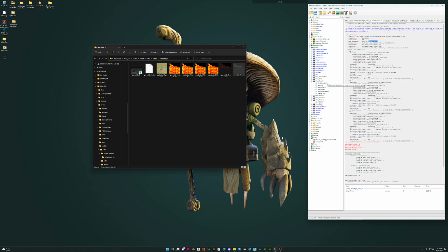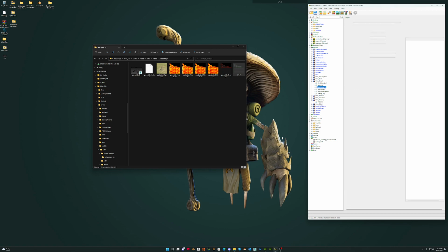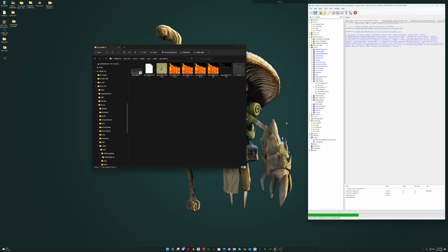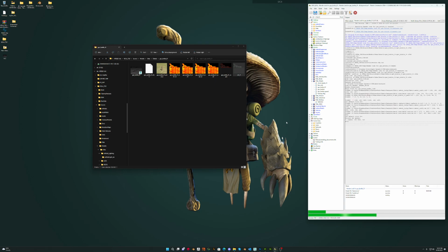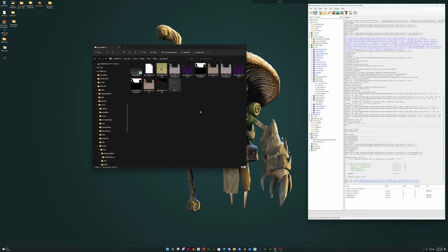So after the first build, it's now time for the TDK to take over and generate this file and this file. Because remember, these are just placeholders. They could be blank files, could be anything you want. So if we right click on that and say render LOD textures, you see it does some calculation. If you get the dots, that's great. If you get plus signs, that's not so good. You see it's just generated the files.